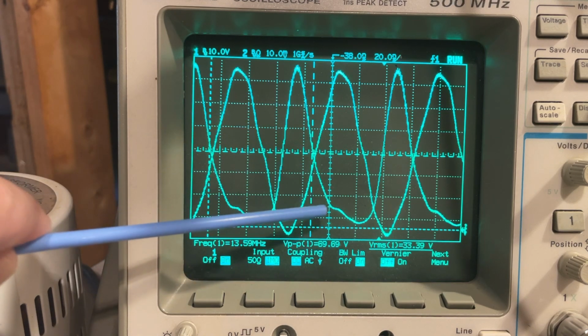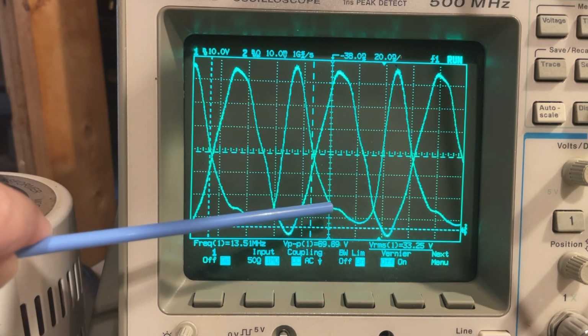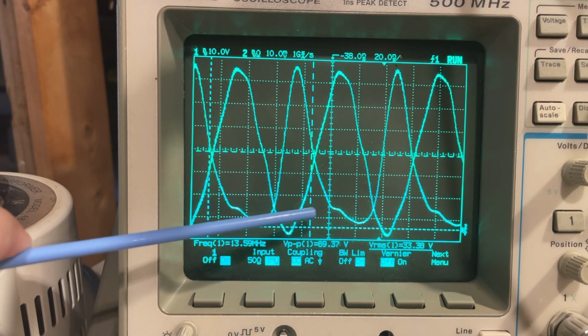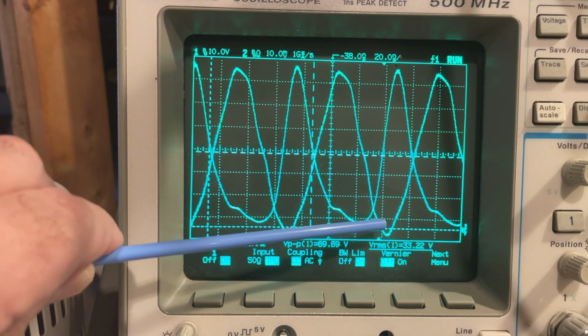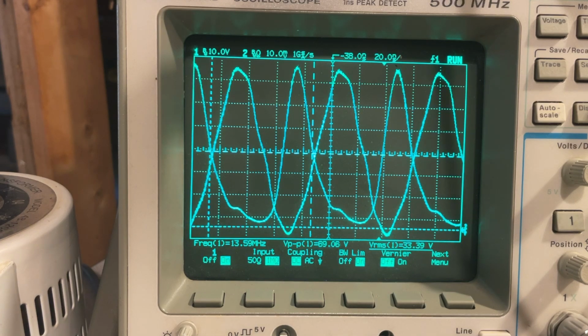So here's where we have some power being dissipated, some power loss, some wasted power. But you can see on the other end, it's very, very little. So we're going to go ahead and measure the efficiency to see how that compares to the Class B and see the type of improvements that we realized. With that said, we should see a much lower operating temperature as well, right? We're dissipating less power in the drain of the transistor, and therefore we'd expect the case temperature to be significantly lower. So I'm going to go ahead and set this up so we can do the efficiency calculation.